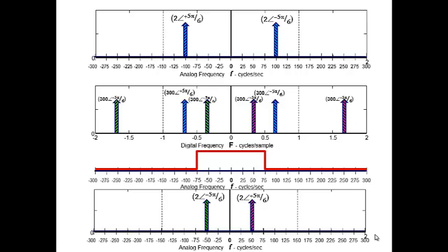You can't make a perfect, sharp cutoff filter. Not only can you not afford it, you just can't build it. It's an idealization, and that's one of the issues. When we get the example finished, we'll talk about how we deal with the practical world where I can't make that filter. Because of that, you can't just sample exactly at the Nyquist rate, and you've got to deal with imperfect filters, and there are some games we play for that.